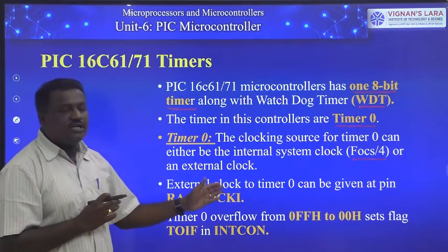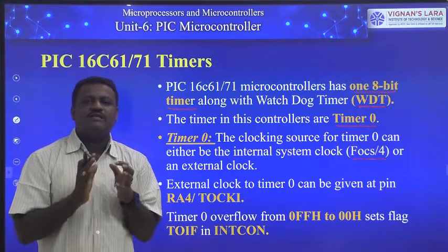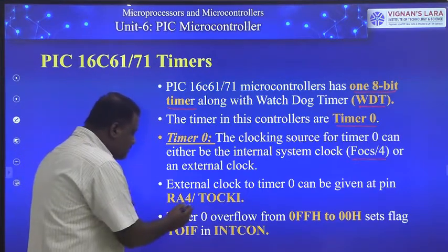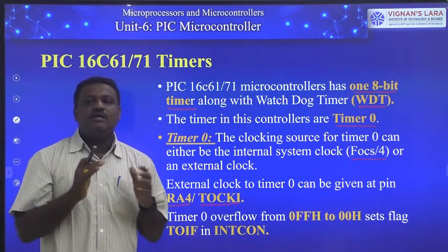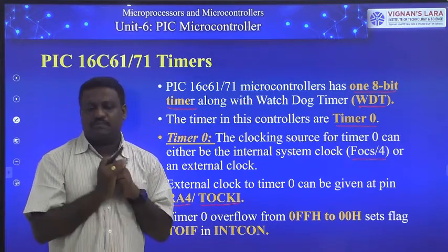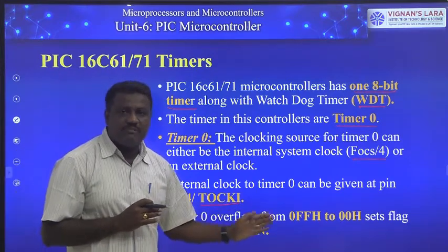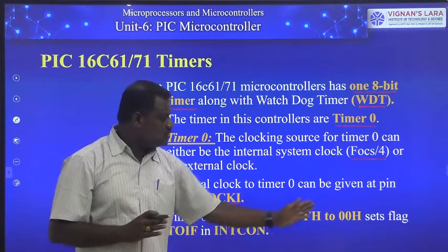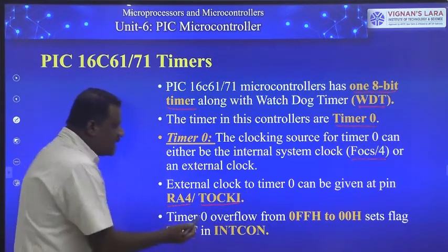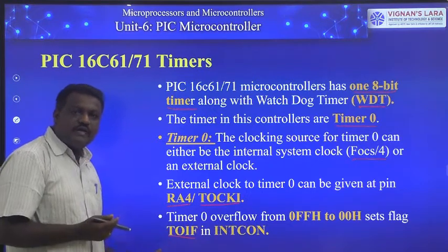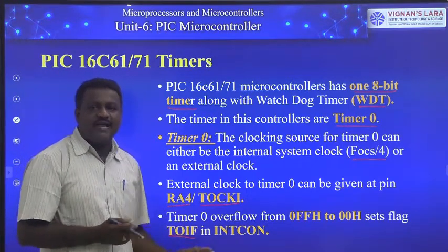Next, the external clock to timer 0 can be given at a port A pin, that is RA4, which is called T0CKI, that means timer 0 clock input. Next, when timer 0 overflows from 0FFH to 00H, a flag in INTCON called T0IF, the timer 0 overflow interrupt flag, is